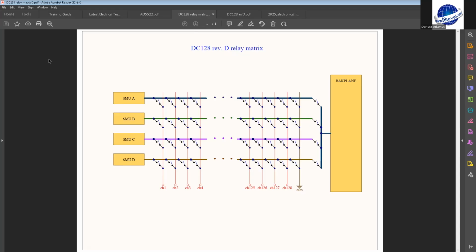With a regular SMU, you can measure something like a diode or resistor. If you combine 2 or 3 SMUs, you can measure transistor characteristics, but measuring the characteristics of an entire integrated circuit becomes very complicated.